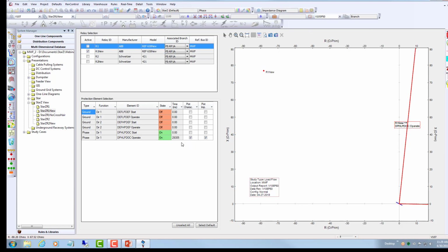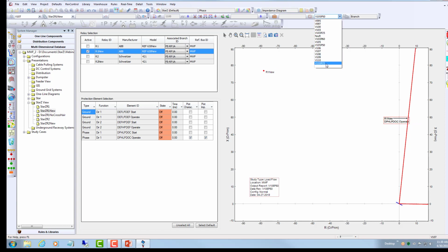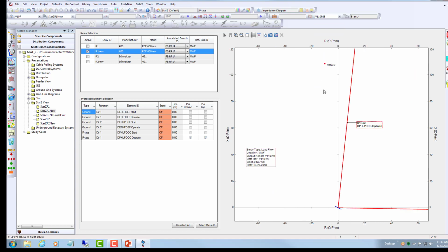Let's look at the other relay. The original settings were tripping at 29 seconds, but the new setting is not going to trip here. You see that here is a circle, not a cross, so it's not going to trip. And the same with the 110% with the 25% generation. So again, it's not going to trip here. By reducing the maximum forward reach, we avoided the false tripping on the most probable cases where there is some level of generation more than auxiliary, but there's an over voltage in the system.